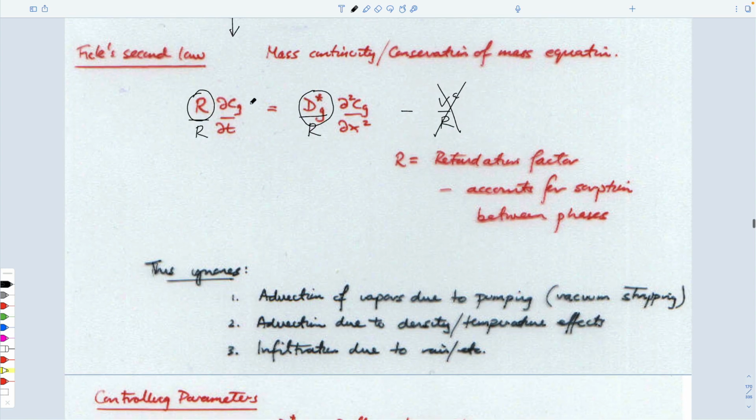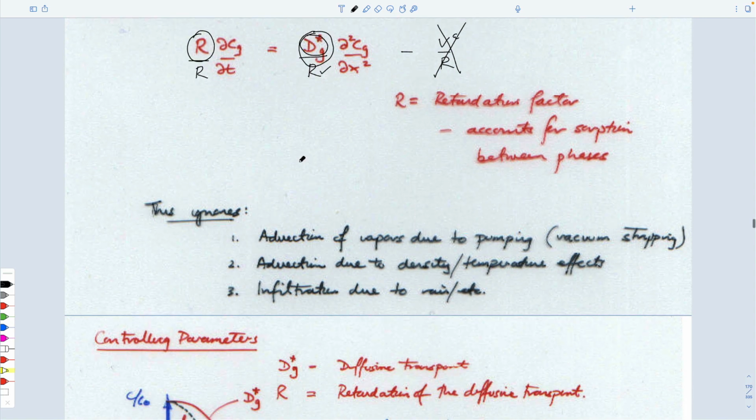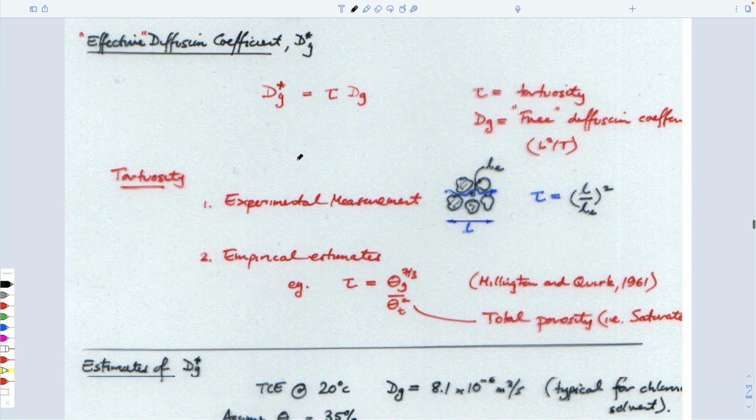So that's the first of the terms that we need to define, which is the retardation coefficient. The second one is the magnitude of the diffusion coefficient. And just like in water, or diffusing in a porous medium, we defined a term which we called omega, which was the tortuosity. Here we're calling it something different, but the same term. It relates to the fact that in going from upstream to downstream, it's not going on a straight path, it's going on a longer traveled path than as the crow flies. And so we have to account for that in modifying the diffusion magnitude.